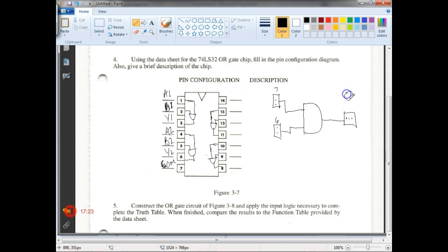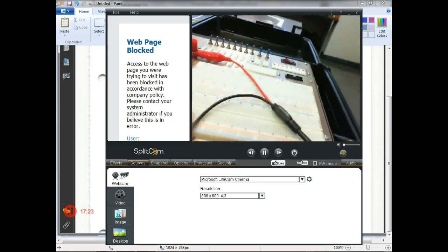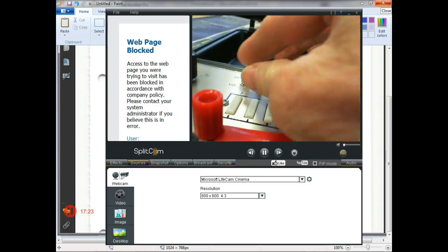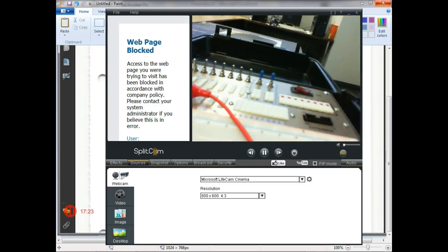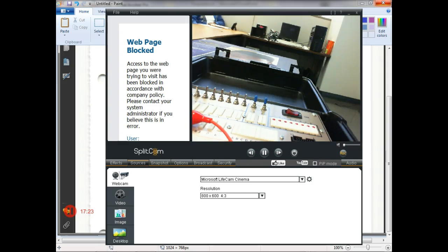And the LED is going to be up here. It's going to be red. Are you okay? Does that make sense? Yes or no? So here's our data switches right here. They run from 0 to 7. Says up is a what? A high, and down is a low. And here's the connection to our LEDs right here. So I should see all highs get a high, right? You understand? So we'll go through 4 combinations because it's a 2 input AND gate. We'll go through 4 combinations, but you should be able to tell all highs equal high.